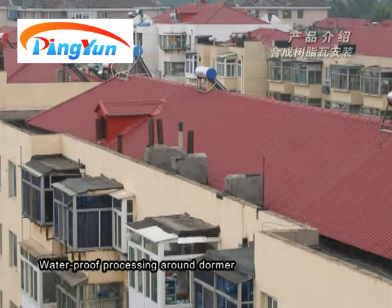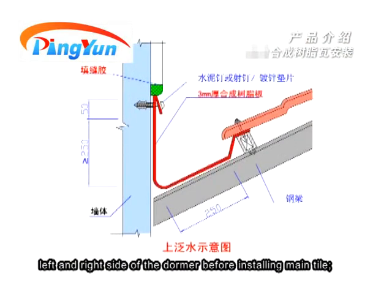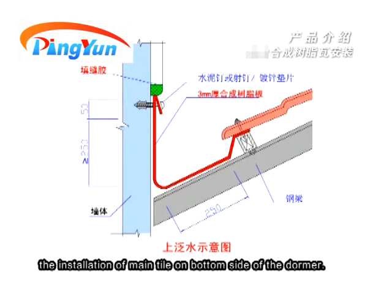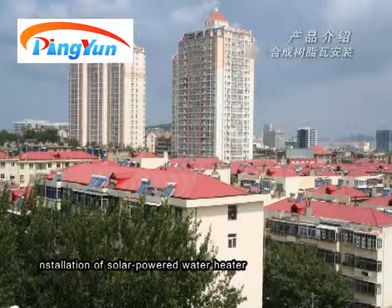Waterproof processing around dormer. The metal or synthetic resin drainage panel should be fixed on the top, left and right sides of the dormer before installing main tile. The metal or synthetic resin drainage panel is installed after finishing the installation of main tile on the bottom side of the dormer.